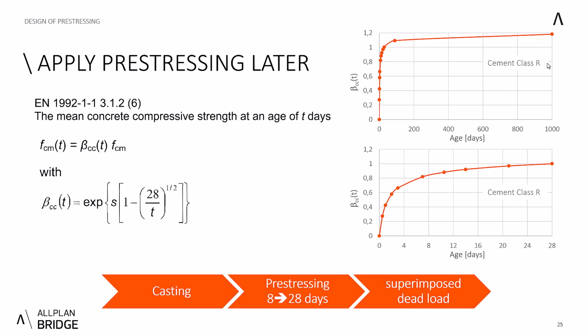Therefore, postponing the application of the prestressing will help to increase the stress limit and may ensure that the stress limitation condition is met. In case of the aging accelerated by the increase in the temperature of concrete, we can input a fictive substitute age of concrete, which is increased compared to the real age.